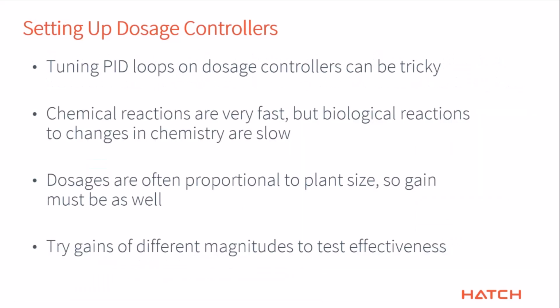Lastly, while talking about that tuning, it is a little tricky because the chemical reactions are very fast with respect to changes in the influent and changes in the biological reactions. So therefore, you have to make sure you don't make your controller too bouncy or too aggressive.